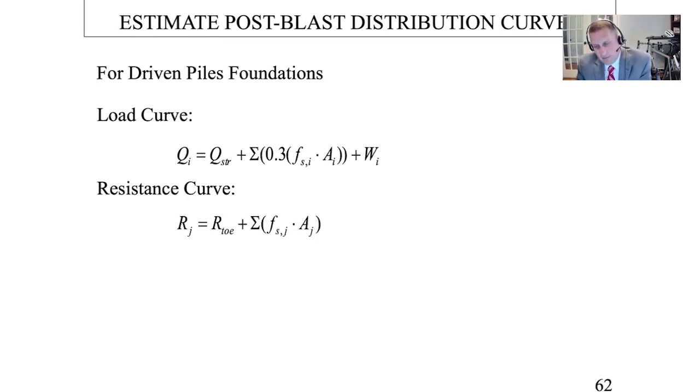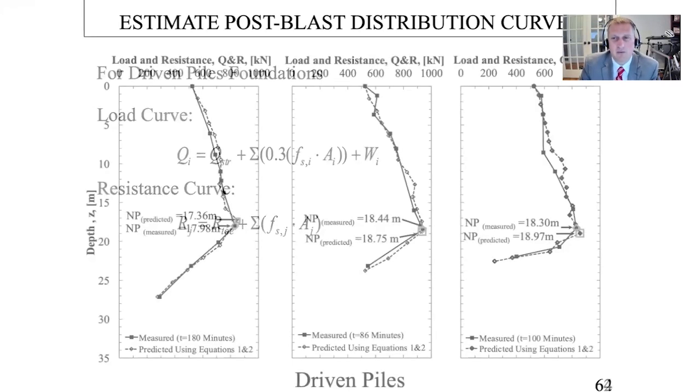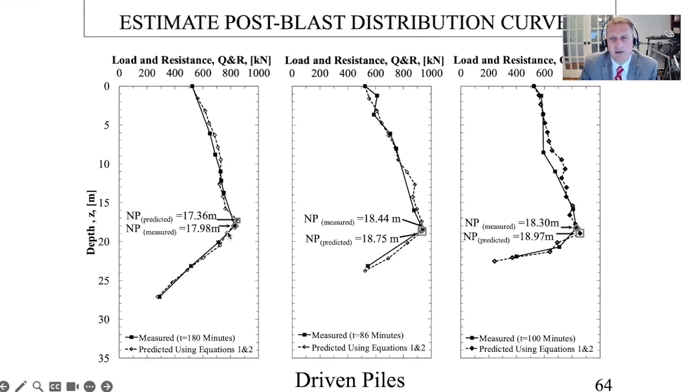What we found, I used the program PHD from Bridge Software Institute to do a lot of the prediction curves. And so if I had used that program, we need to modify the load curve by about 30% in order to predict what we would get out. Just looking at these two curves, there's a 30% difference if I use the PHD software program to predict the amount of load as compared to what we had. And so by modifying it, here's the measured and predicted with that 30% modification on the amount of load curve that's there.